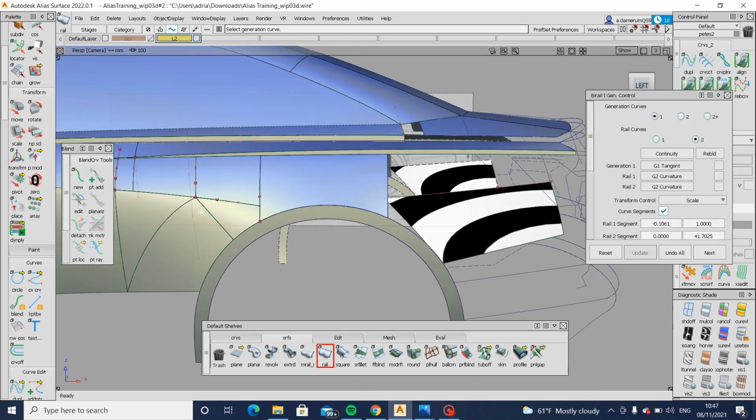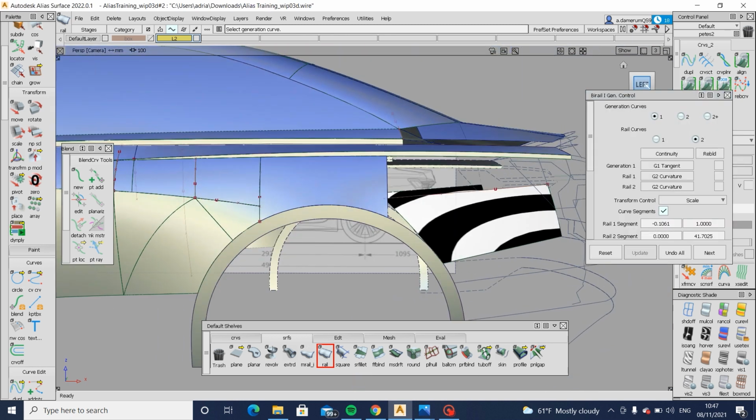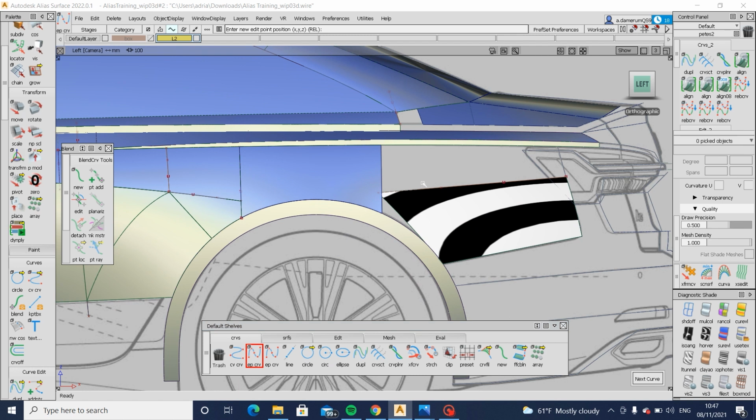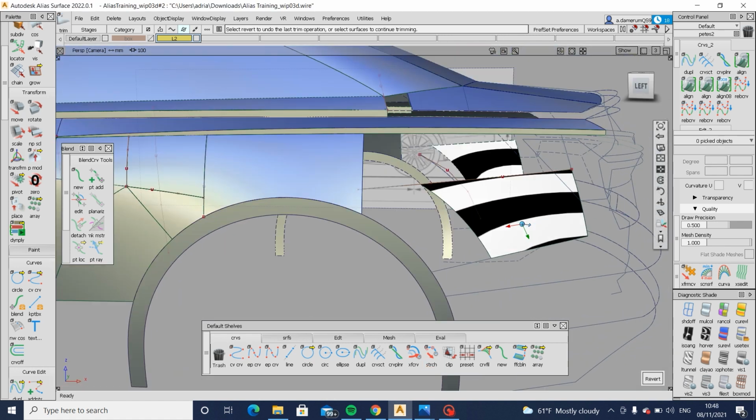And then what we'll do is build this surface in. So let's build it around there. Get it to mimic the behavior of the wheel arch. Project and trim. Just get that, yeah. Trim that away. Okay, and then like I did before, I just built a skin from there to there and blended, and then I'll build that square in. So let's do that. A skin.